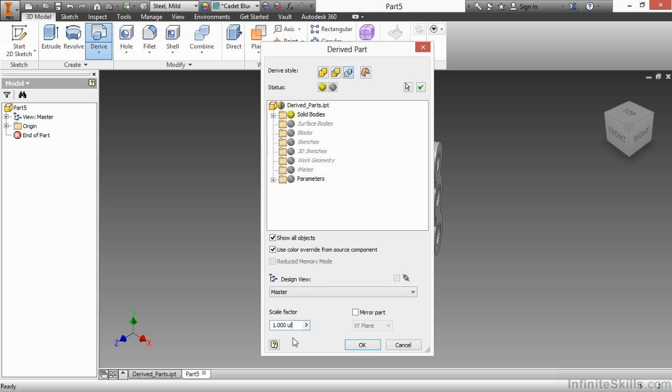Let's say this goes through a heating process or a cooling process, or some other sort of process where my isotropic shrinkage is adjusted somehow. So maybe I want to scale this up or scale it down by a certain factor. I can put that in here as well. Maybe it needs to be mirrored. I can do a mirroring of this operation and mirror it across one of my standard planes.